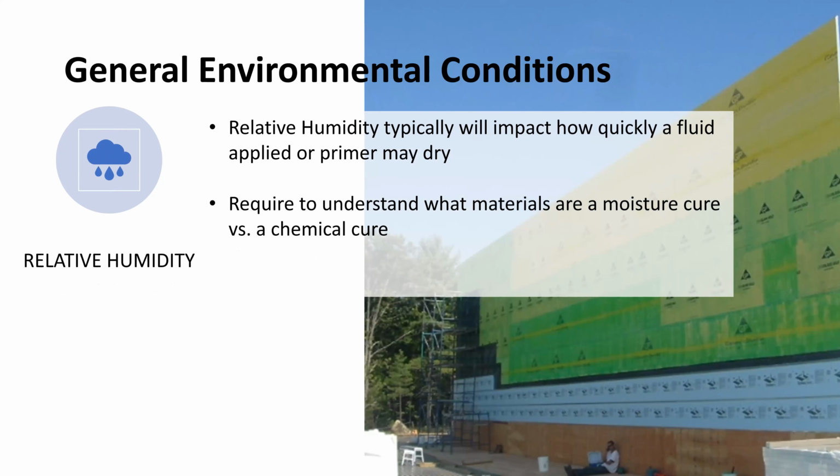Now, from a relative humidity standpoint, that tends to be basically kind of like temperature, right? There's going to be some relative humidity conditions for some of these materials, and it's really going to impact how quickly things cure. So again, if we're using something that's more water-based, it's going to take longer for these materials to cure.